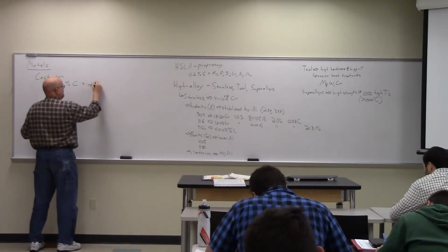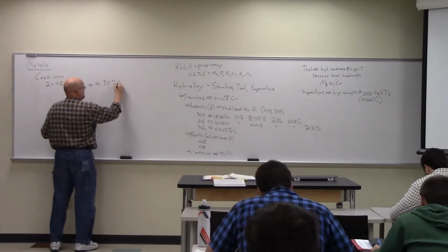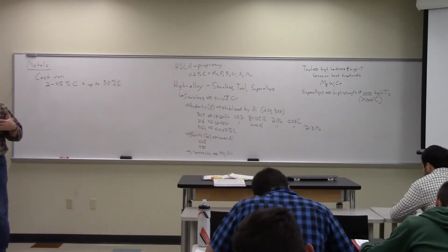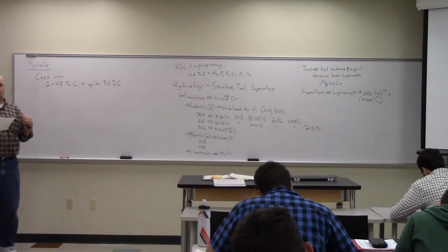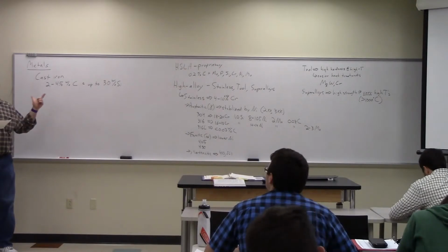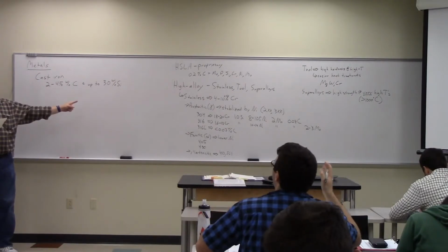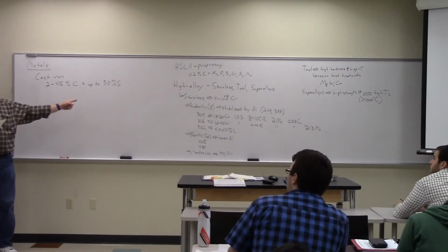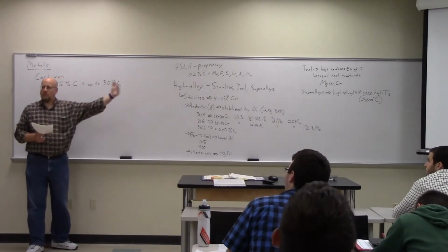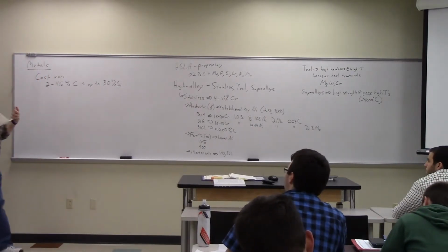And up to some, depending on what you need, 3 weight% silicon. The silicon facilitates the formation of graphite. Okay, remember I told you in the iron-carbon phase diagram, I said, unless we go really slow, what's the right-hand side? Cementite, right? Fe3C. But if I throw a little silicon in there, I can cause graphite to be the second phase, not Fe3C. At least to some extent.